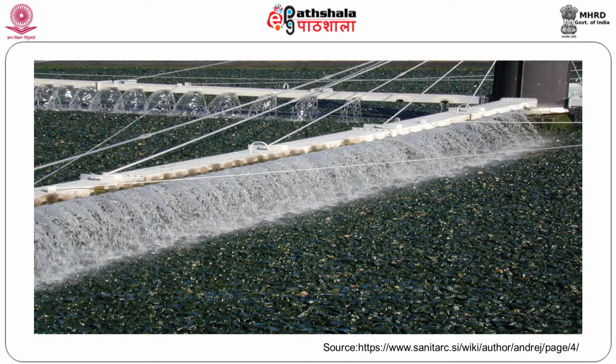So, the driving force responsible for migration of oxygen from atmospheric air to the pore space of the packing media is the partial pressure gradient. Once oxygen reaches the pore space, further migration towards the biological film is due to the DO deficit in the bulk fluid. The rate of mass transfer from pore space to bulk fluid is related to the DO deficit in the bulk fluid, and the deficit is quite high here. Once oxygen is transported into the bulk fluid, further migration occurs because of the concentration gradient within the liquid film. Once it reaches the liquid film, it then goes into the biological film. In the biological film, plenty of bacteria, billions of bacteria, are residing. They require molecular oxygen as a terminal electron acceptor.